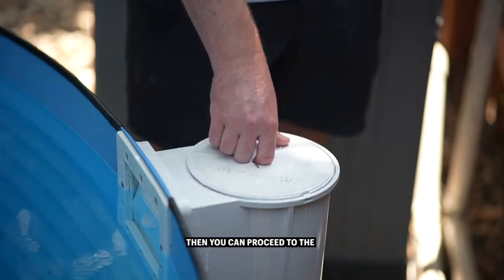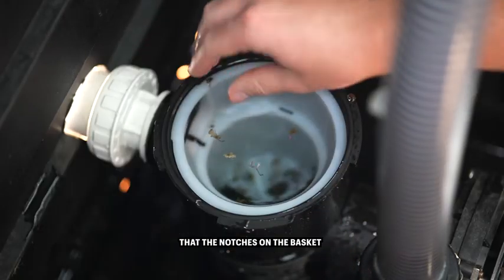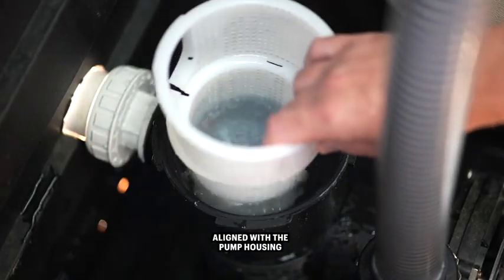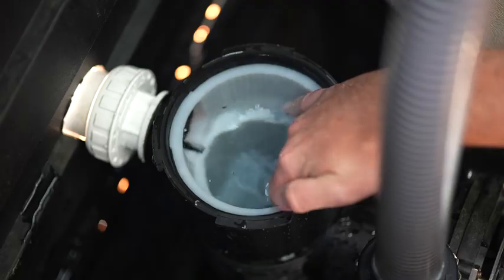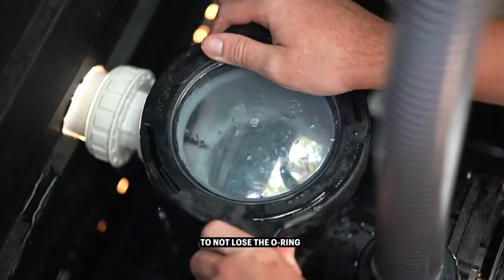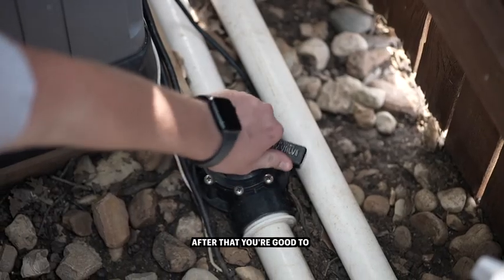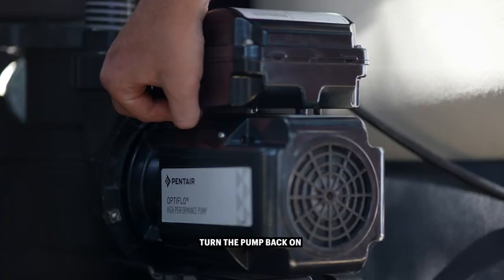Then you can proceed to the pump basket. You'll have to open the pump lid and take out the debris. Make sure that the notches on the basket align with the pump housing when putting it back in. When putting the pump lid back on, make sure to not lose the O-ring inside the lid, as it is essential for proper sealing. After that, you are good to open the suction valve and turn the pump back on.